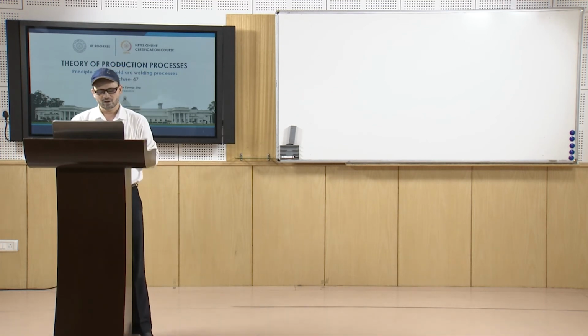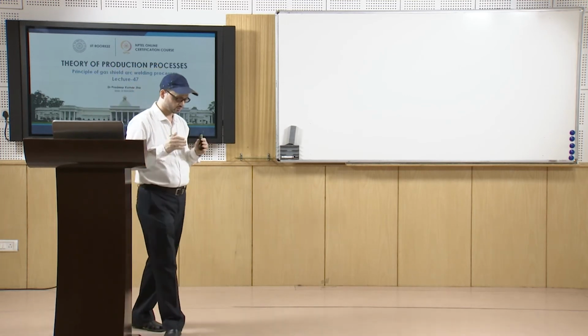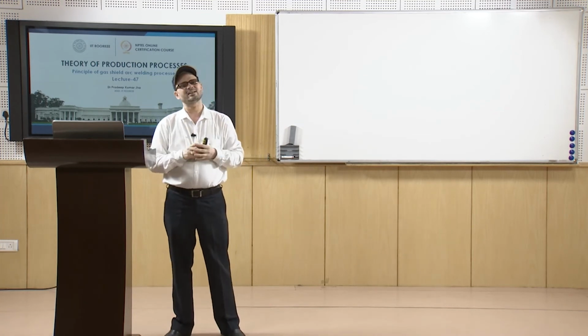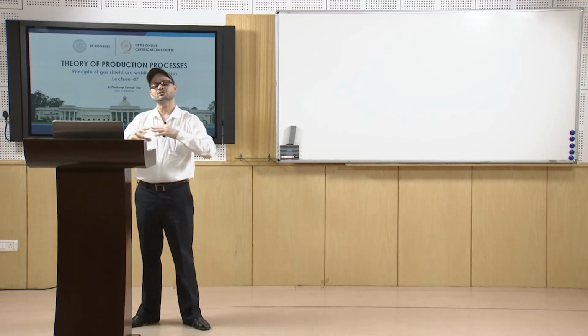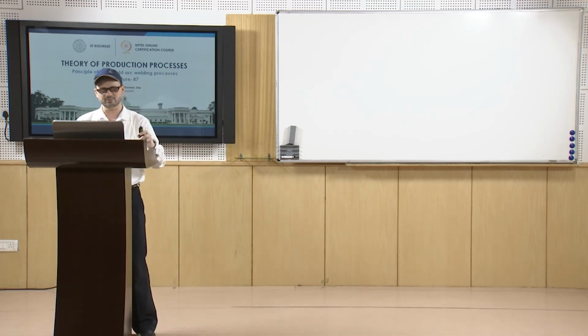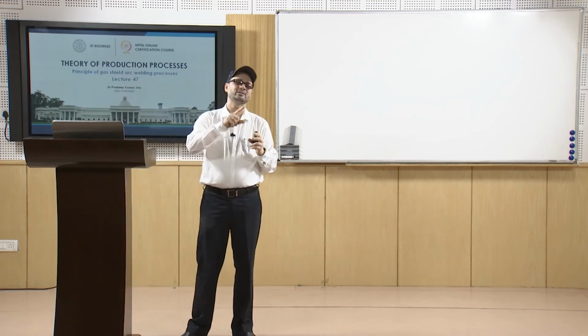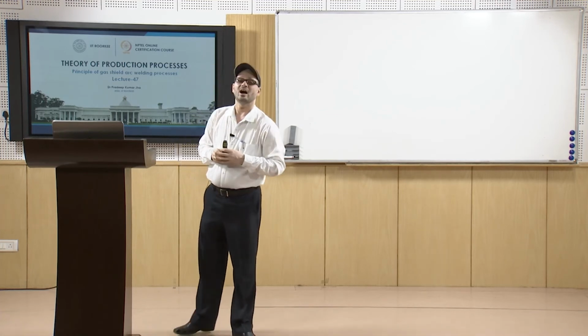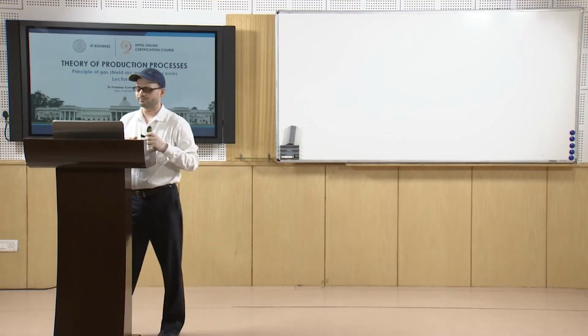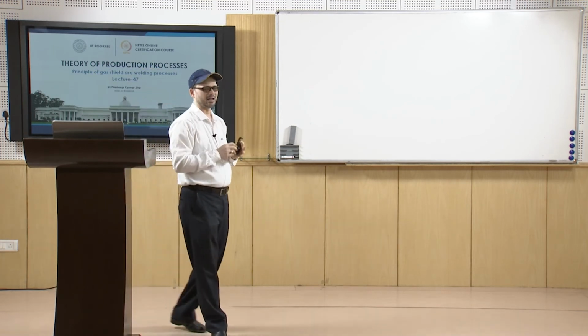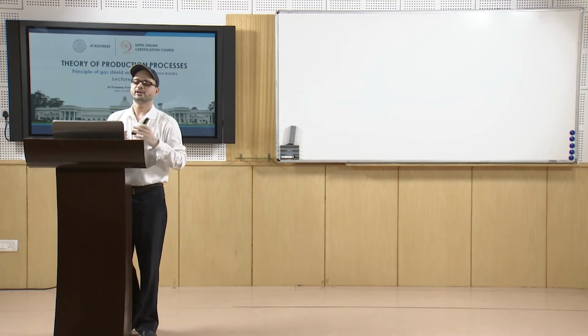Because of that the current setting has to be higher in those cases, maybe 20 to 30% higher as compared to the case of helium or argon. That is another factor to be taken into account when we use carbon dioxide as the shielding gas.